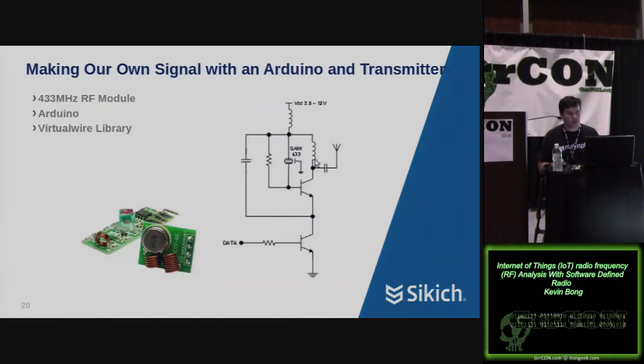If you look at this area here, this one thing right here in the middle is a 433 megahertz crystal. That's this right here. So it's a slice of quartz shaped and tuned so if you start it vibrating, it's going to vibrate at 433 megahertz. And this circuitry around it, with these two inductors here, is really just meant to cause that to keep oscillating at that frequency. So it reinforces, yes, you should oscillate at that frequency, and here, make yourself a little stronger and things like that. So that's what's happening here.